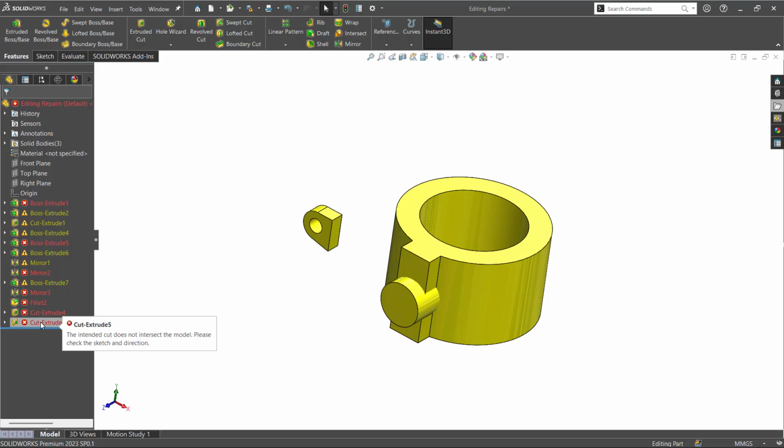What I would recommend is to always start from the first error in the model. Why? Because if you solve the first error, it might even solve most of the other errors in the model. So instead of focusing on each and every error from the bottom, better to focus on the first one in the chart. Now these are the warnings. They are telling us these are okay, meaning I can accept the model with the warnings and I can run this model. They are pretty fine, and you can even remove them, but it's not mandatory. The model is fine with the warnings, but errors you must and should clear.